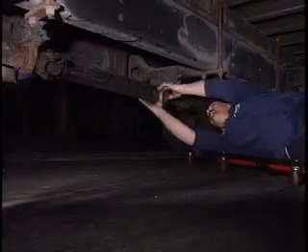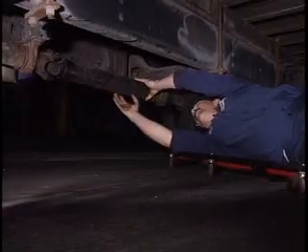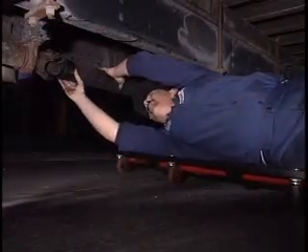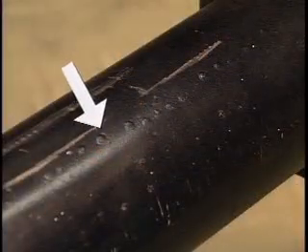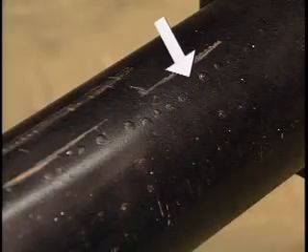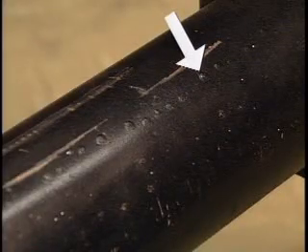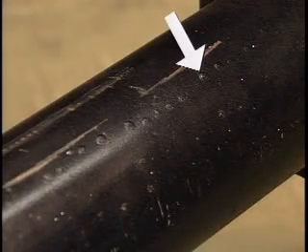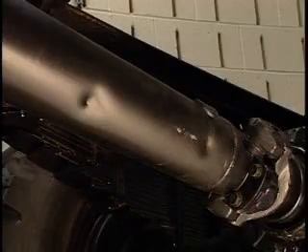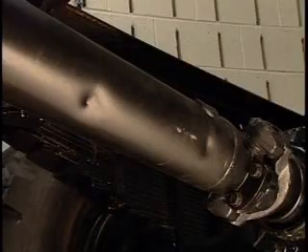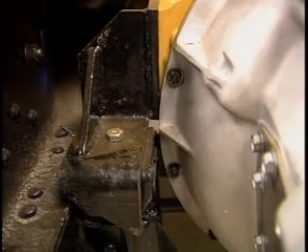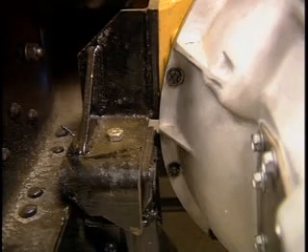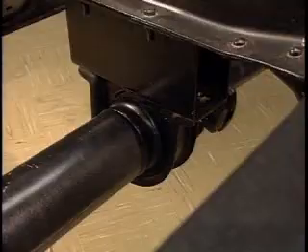Driveline troubleshooting should begin with an inspection of all the driveline components for possible causes of imbalance. Look for an uneven buildup of paint, undercoating, or mud that could throw the driveline out of balance. Also, check for missing shaft balance weights or damaged driveline components. Check the engine and transmission mounts to ensure the power package is still at the angle the truck manufacturer intended.